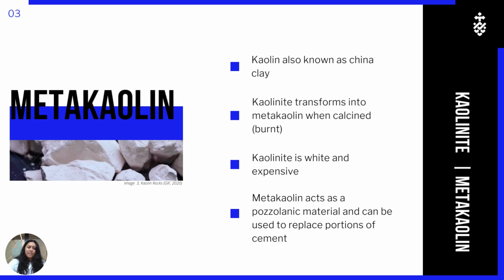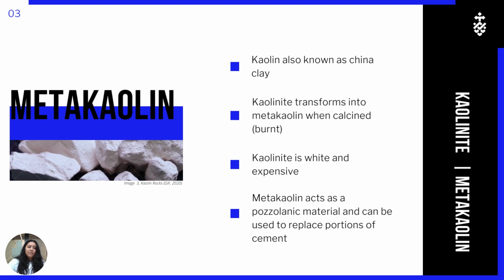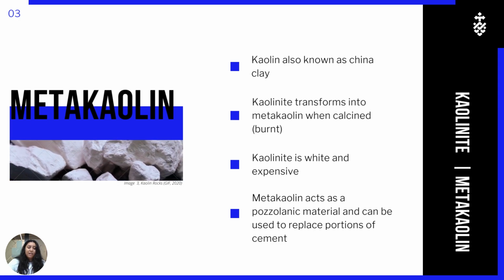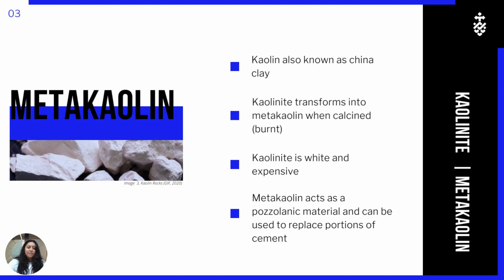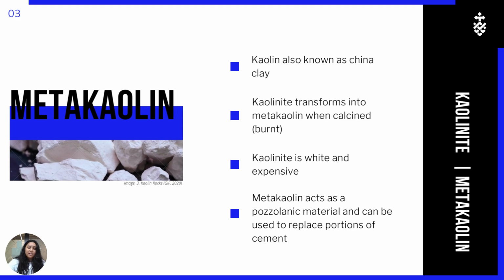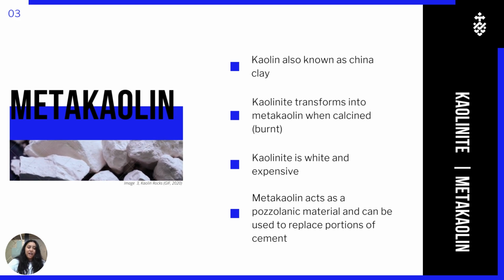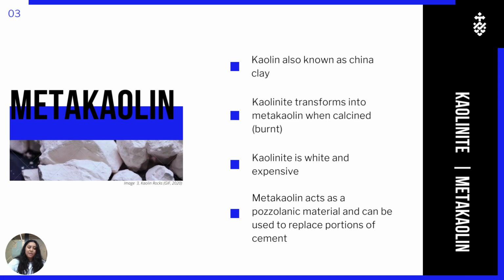Kaolinite, however, is very expensive, and the mines in which this pure kaolinite is found use it to produce products such as paper, ceramic, paints, etc. Therefore, high-quality kaolinite pits are sought after, and they're quite high in demand. However, prior research suggests only 40% of the clay needs to consist of kaolinite in order to create a concrete technology that can outperform traditional GP cement.